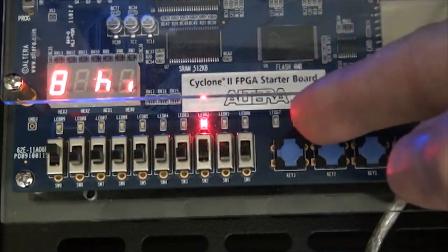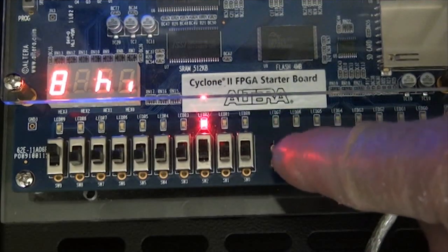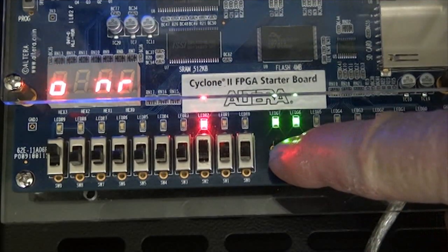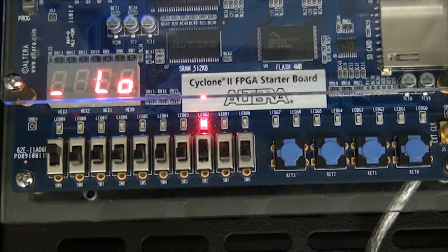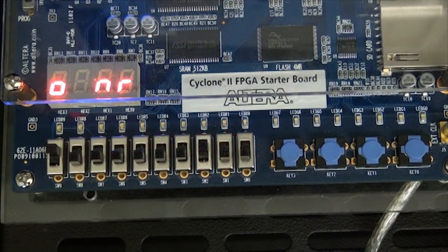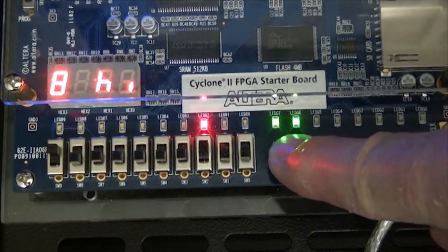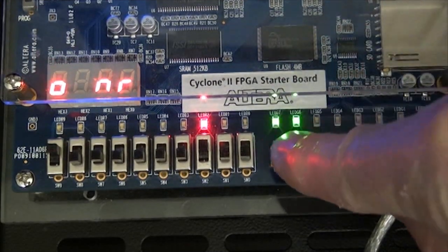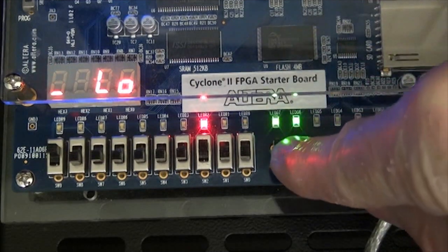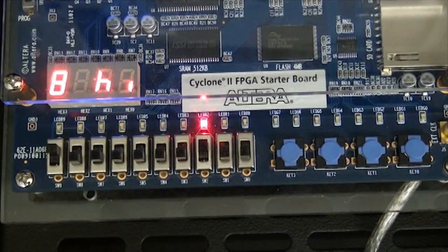When I do this, you're going to find that if there's no more motion detected, 5 seconds after the last push of the button where the green LEDs come on, if I let that go and wait 5 seconds, this light will go out. Now in typical applications, that time will be a lot longer. It could be maybe a minute, 2 minutes, where there's no motion detected in the room, and the lights will go out. So if I press this again for another 5 seconds, if I continually push this within that 5 seconds, when I let it up the last time, then 5 seconds after I let it go, this light will go out.